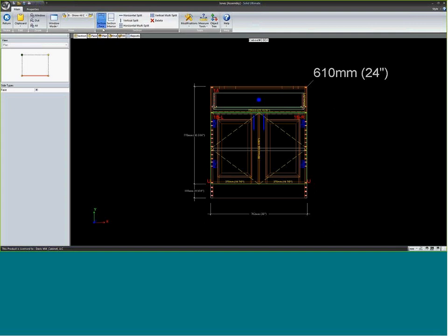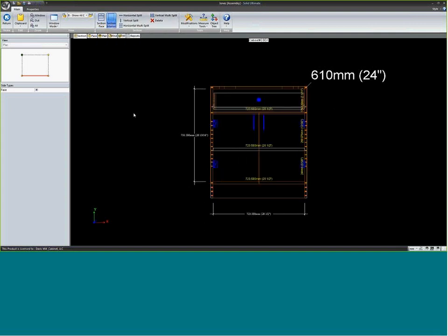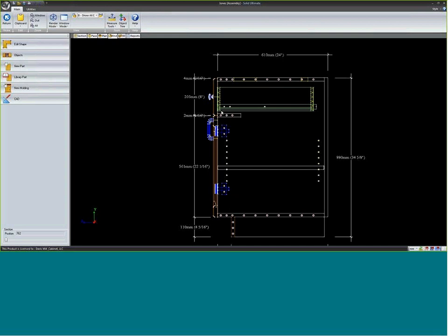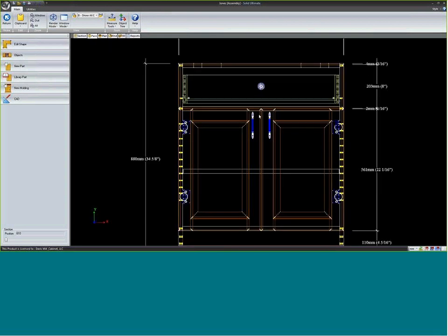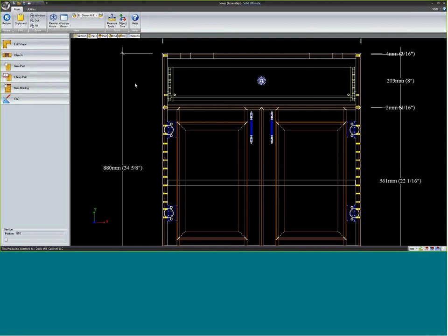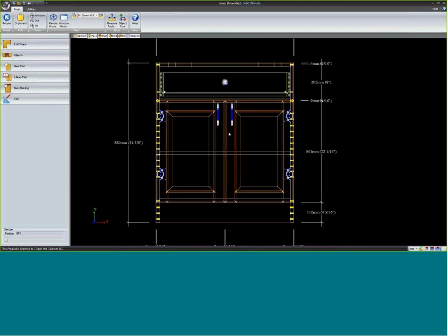So let me go cabinet level though, because now I'll section the interior. There's a couple things in the interior you might do to a cabinet. For instance, if I look at my end view, I've got a little drawer stretcher here. That stretcher is basically there to give the doors something to close against. But sometimes somebody will put an item down here, a trash bin or a Mig lift or something, that they don't want anything from this drawer to be able to fall down in here.